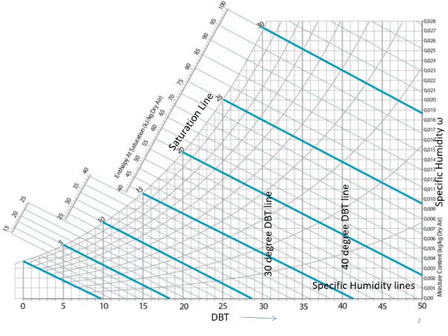Now below that there are similar curves. All those curves or lines are called relative humidity lines. The saturation line is 100% relative humidity. The very next line below that is 90% relative humidity or 90% RH. Below that 80, and below that 70, 60 and so on.